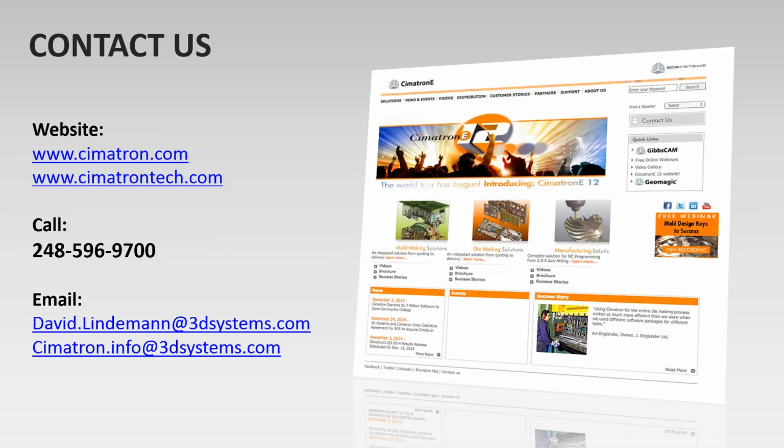Is Cimatron useful only for creating conformal cooling, or do you do other mold-related functions? We do other mold-related things. We have a complete set of tools for mold design, which includes all your standard components in the industry and catalog, or the ability to create your own mold sets, as you will. You also have standard water lines, runner lines, ejector systems, the ability to place ejector pins, all that. So it's what you'd call a full design package, as well as splitting and looking at the slides and lifters associated with the part.